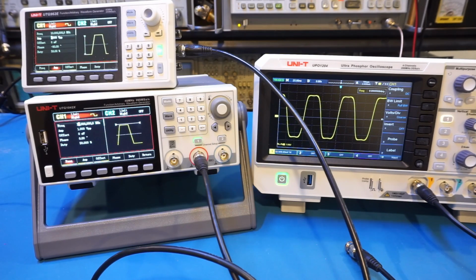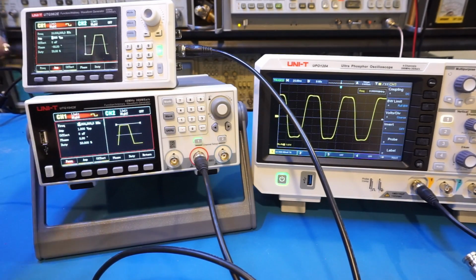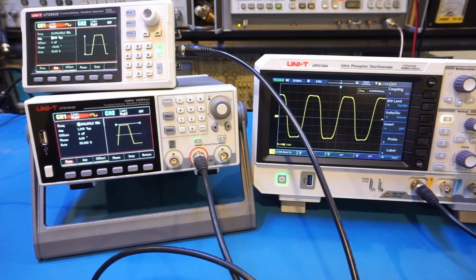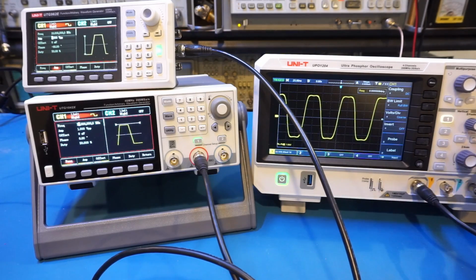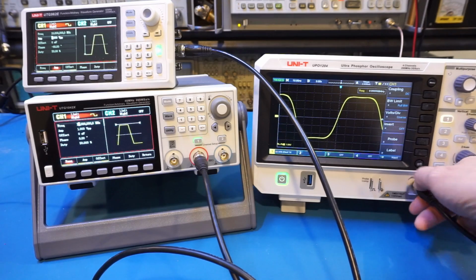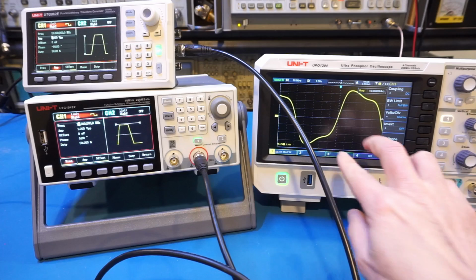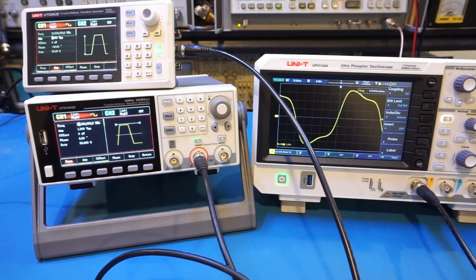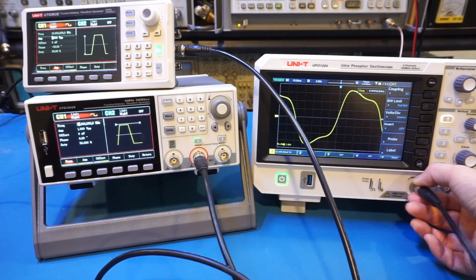And just out of curiosity, let me swap in the signal output from the 962E, and now I have adjusted it to output the same 10 megahertz 1 volt peak-to-peak signal. So let's take a look at the slew rate. Actually, let's just concentrate on the rising edge here. So let's see here, it's roughly 2 divisions. And let's swap in that signal here. And you can see that we have pretty much the same slew rate. Of course, there's a little bit of a difference in the frequency response, but that is irrelevant in this measurement.